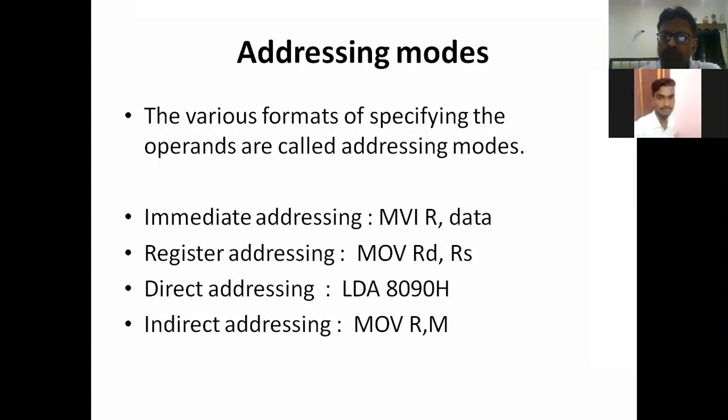And this mode will be used whenever we know the actual data. If we know the actual data, then we will be using immediate addressing mode. And the example of immediate addressing mode is MVI R, data, 8-bit data.